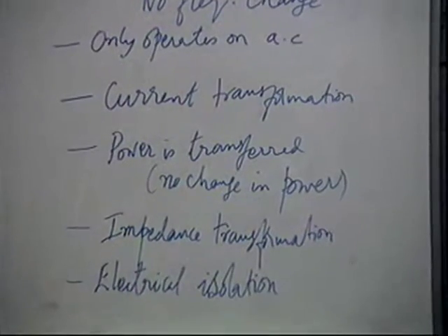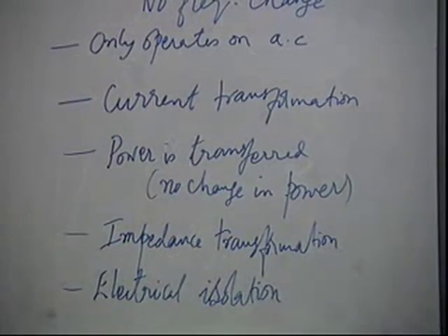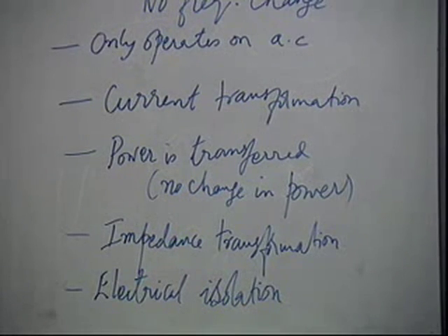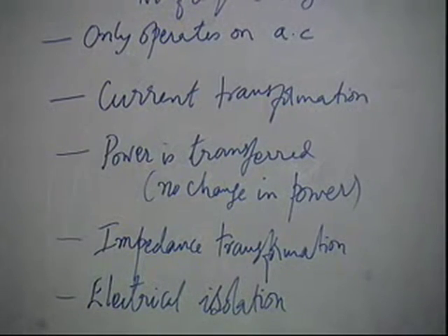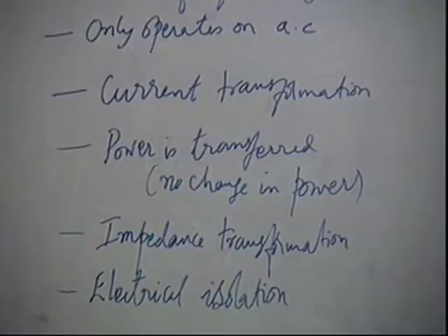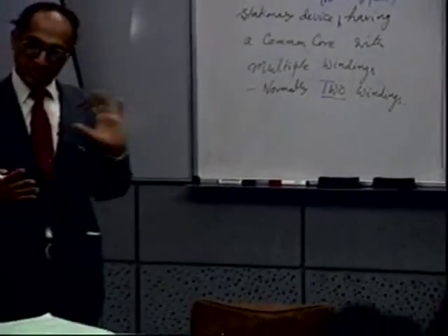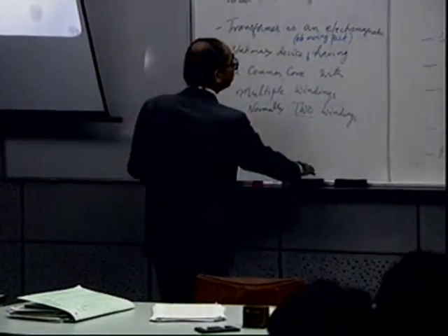Okay? So can it induce a phase change? Yes, it can. We will see that it can induce a phase change depending upon how you connect them. Either they can be in phase or out of phase by 180 degrees. Okay? Ideally, the phase change between the voltage on one winding and another is generally either 0 or 180 degrees. Okay? You can't say I will have 55 degrees. For that you may have a combination of factors, but that's a little complicated issue. Okay?